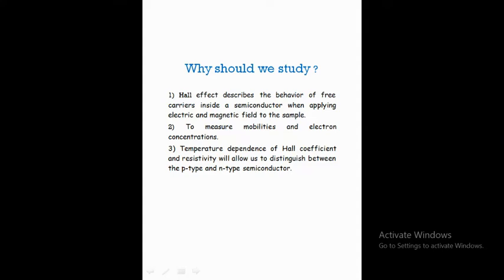Because the Hall effect describes the behavior of free carriers inside a semiconductor or a material when applying an electric and magnetic field perpendicular to each other to a sample. The Hall coefficient measures the mobilities and electron concentration in the sample. The temperature dependence of the Hall coefficient and resistivity will allow us to distinguish whether the semiconductor is P type